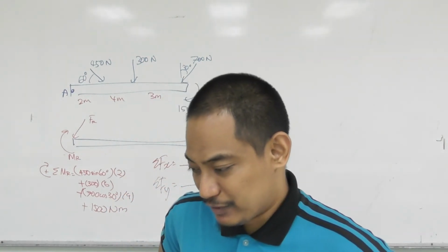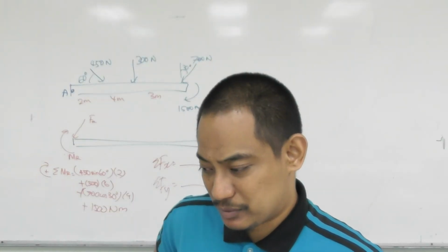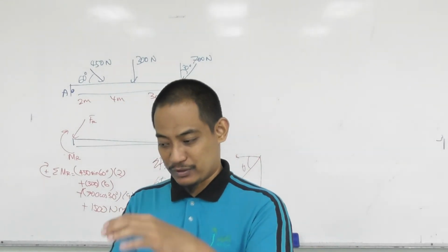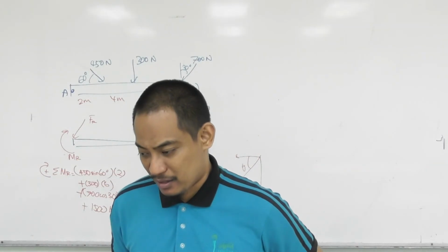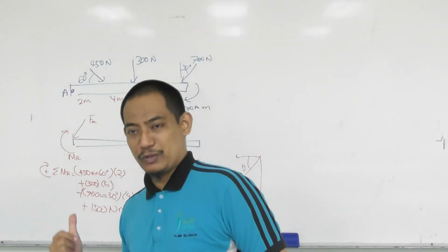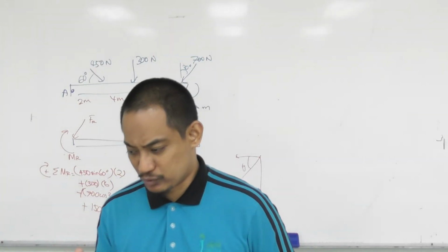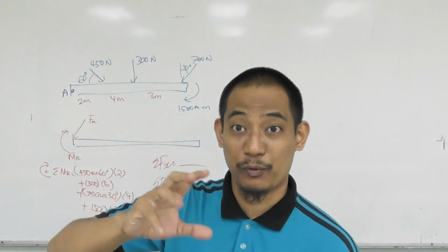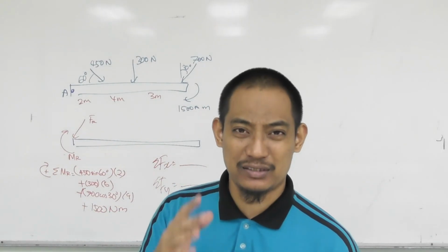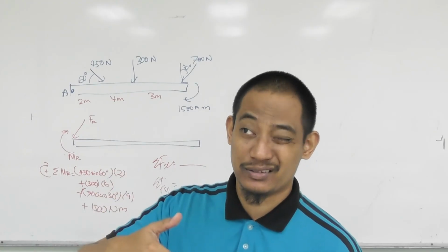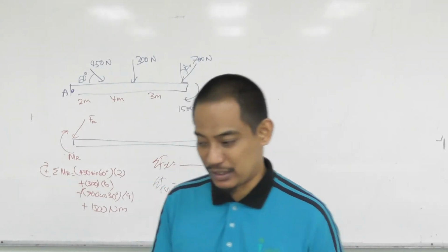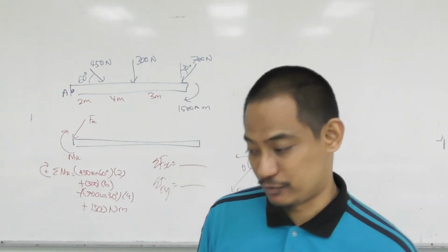However, this one is interesting for those who haven't tried before, because they have the pipe and the moment. It's tricky to draw on the whiteboard. The moment has some angle that you have to project to get the XYZ components. The way you project is exactly how you project a force, using the angle, etc. In the end you will get XYZ components for each moment.